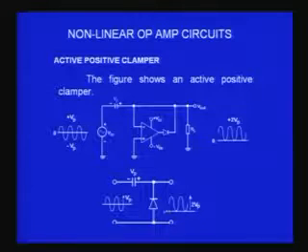So the output will start going from 0 to 2 V peak as the amplitude, and therefore what I have effectively done is I have clamped this 0 line at the bottom, so it becomes fully positive and it is a positive clamper. So the output signal has got 2 Vp as the maximum voltage. So this is a normal diode capacitor based clamper.